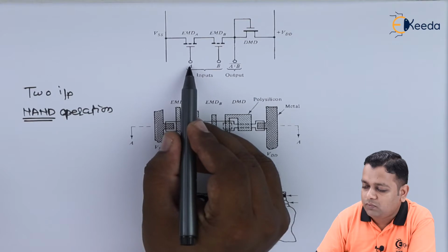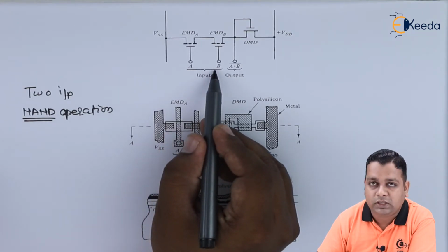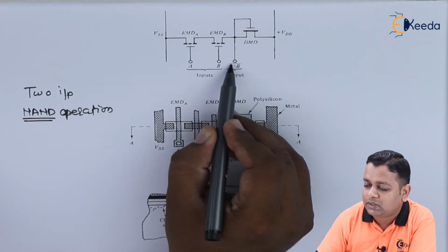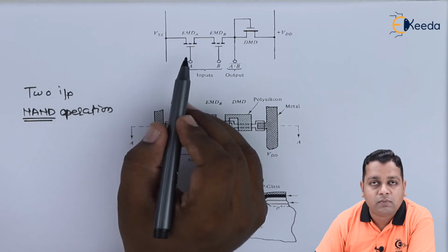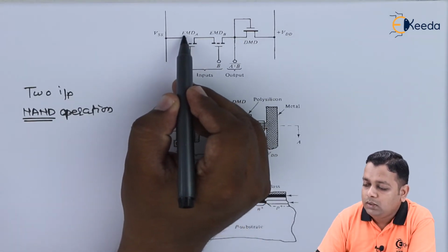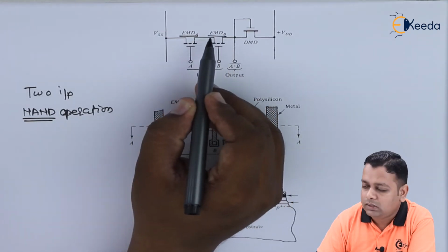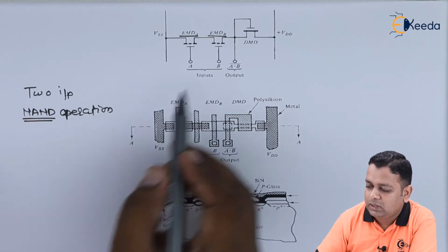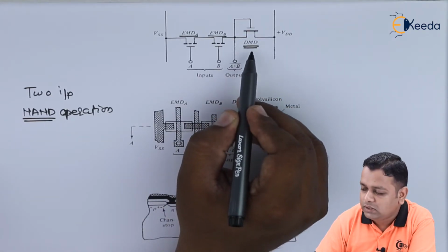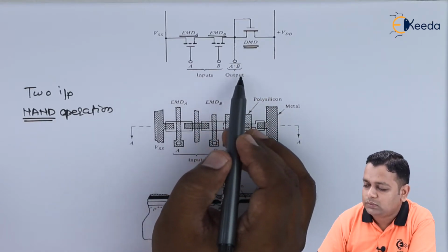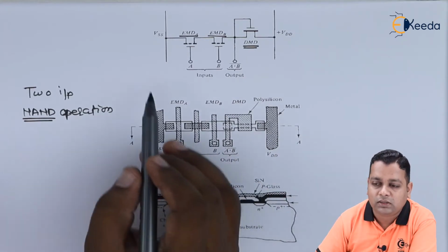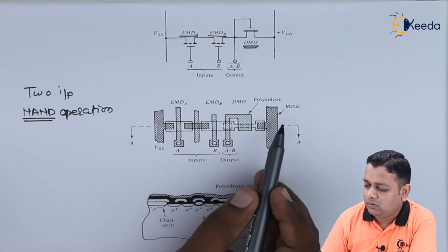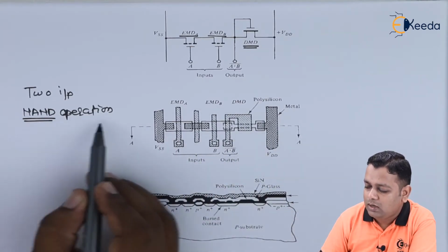These are the two inputs that we can designate with capital A and capital B. The dot representation is the simple multiplication of the two, that is the AND operation, and the negation is represented by a bar over it. In the first schematic we have the fabrication of the enhancement MOSFET for A and for B. These are the two MOS transistors used for this NAND operation, and the depletion type device is used for obtaining the output at this particular place. This is another diagram explaining the same thing, with the schematics shaded corresponding to the different devices involved in the NAND operation.